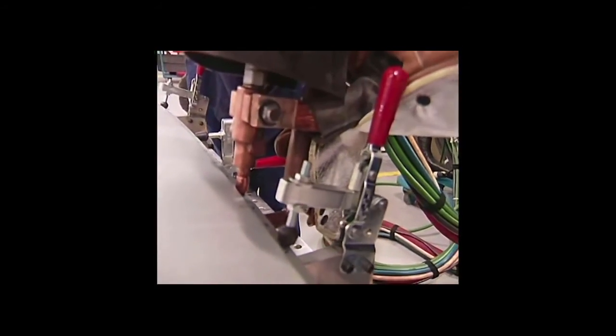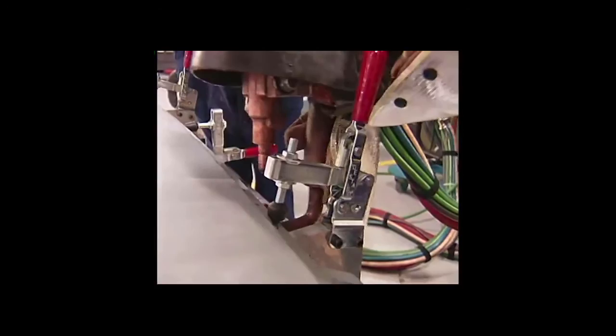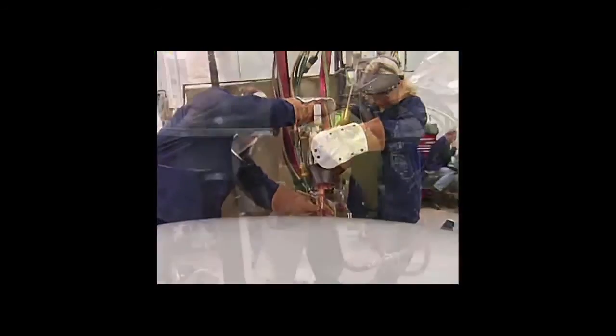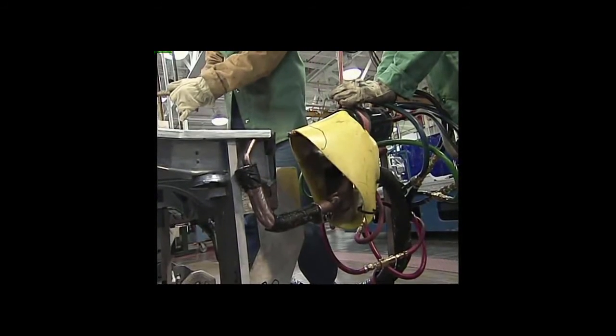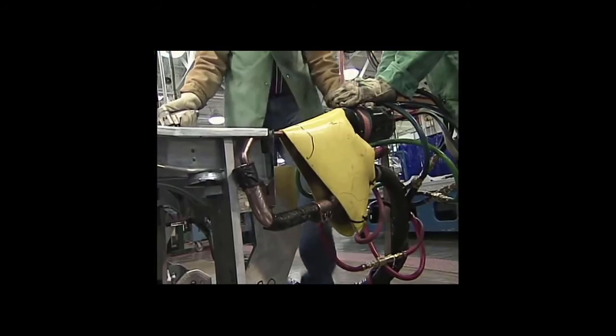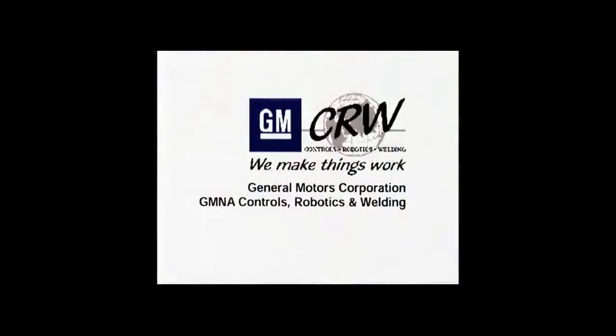At General Motors, we use a specific squeeze force setting, which is dependent on material type and thickness. This value is a critical requirement for consistency in spot welding. You can find correct force parameters along with weld time and weld current values in the WS4 specification.